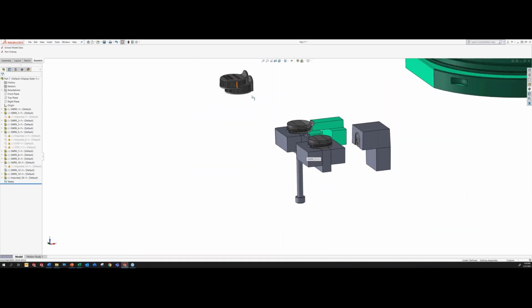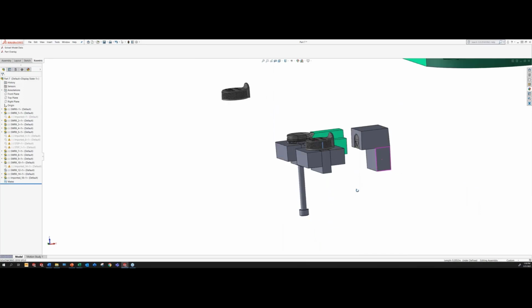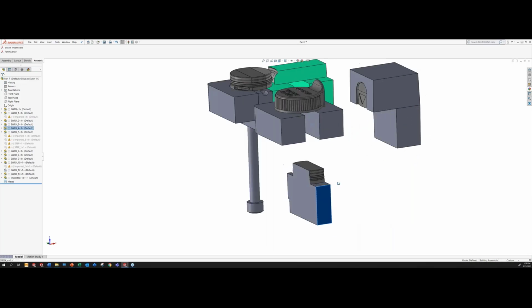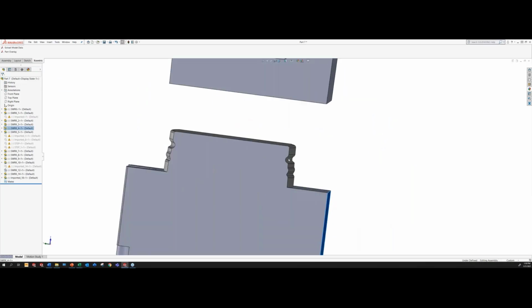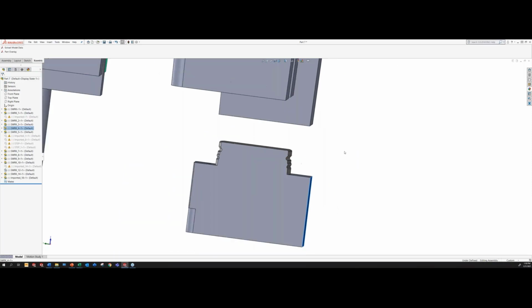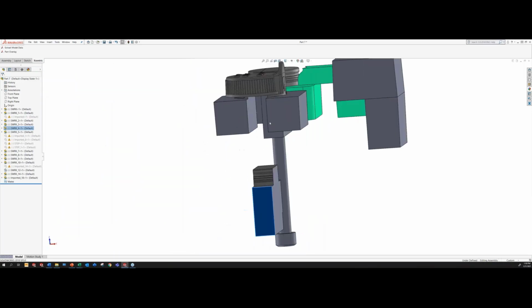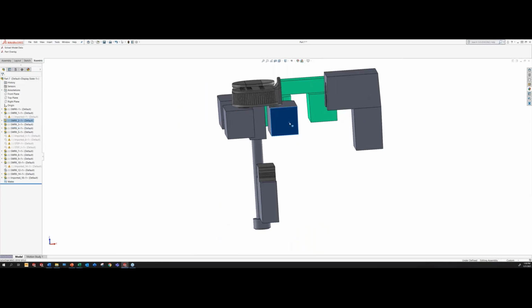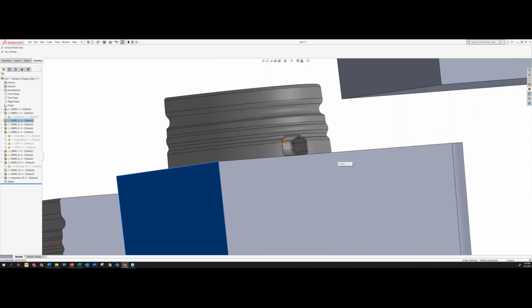So imagine the part is sitting on here. What the operator has to do is essentially pull this first piece out, and there are undercuts on it. You can see here. It's polypro, so it is flexible. So it would strip out, so the part would be left like that. Then the operator would have to push the hand load in and then pull out to capture this lock feature here, because this would not be strippable.